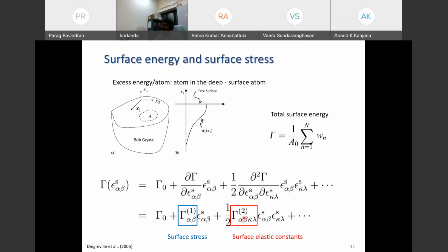This is what gives rise to the different elastic behavior of the surfaces, and you can connect it with the atomic arrangement of the surface. Because the atomic arrangement is different, naturally you can expect different elastic properties there. But remember, it's not really a big volume over there. It's typically only 1 or 2 atomic layers thick. So it's not truly a bulk or volume type of elastic tensor, but a surface elastic constant. It's for a membrane.